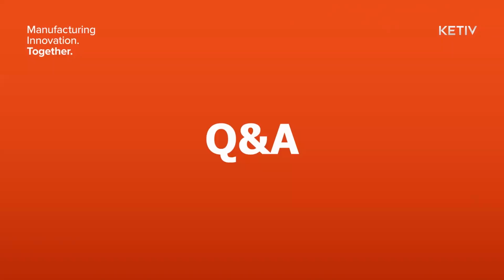This question's coming up a lot, from direct chats and in the Zoom chat: Inventor and Revit functionality. The way Inventor and Revit work, and correct me if I get out of line here, is that in Inventor, you can certainly send stuff over to Revit, but you use what's called the BIM content or the BIM exchange to move that stuff from Inventor to Revit. So you don't use this Factory workflow to do that.